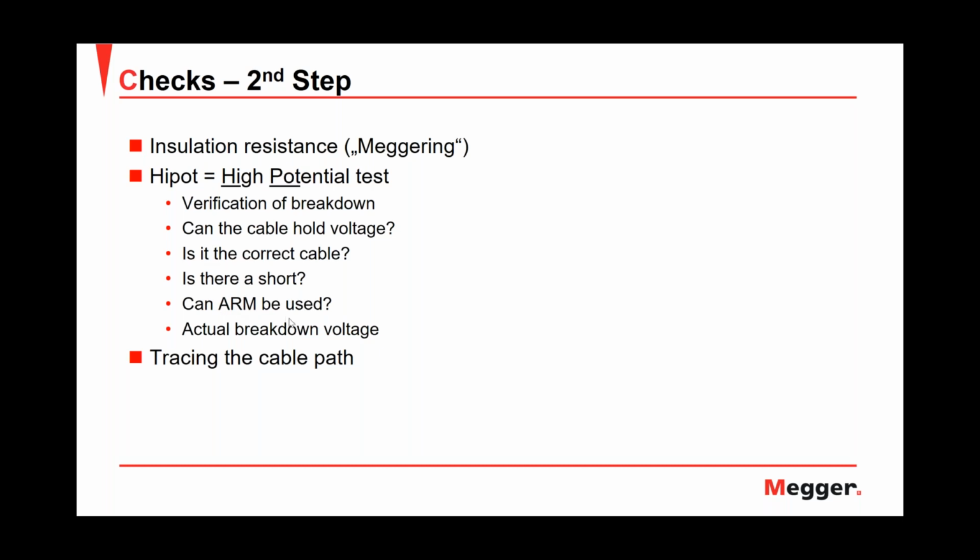For instance, let's say that I'm doing a hipot test, and I have no idea what fault my cable has. So I will do the hipot test, and what I see is that I cannot charge my cable, which means that the needle of the voltmeter in my thumper will not go up. Okay, so I cannot charge the cable. Then how will I answer the questions?